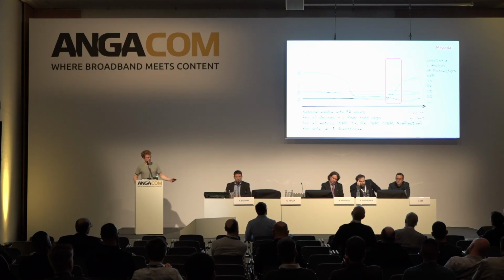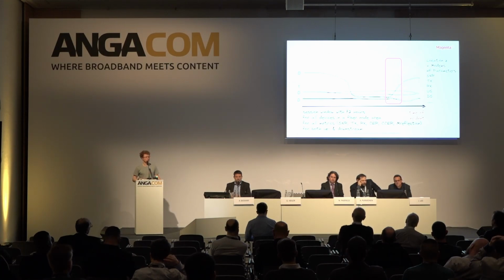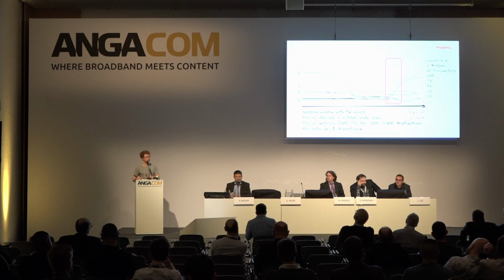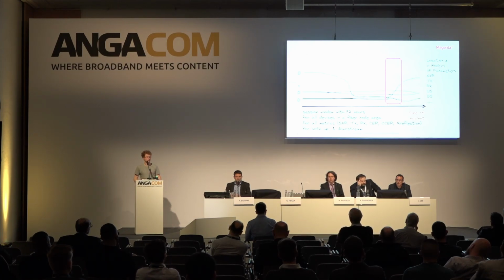On the x-axis, we see time as an abstract notion, where we have the state of the last 72 hours of telemetry data in the network leading up to the incident. We have many devices, all devices in that specific fiber node area, and multiple metrics for each device, being SNR, TX, and all of the PNM metrics you can imagine, in an aggregated way at the level of a last line amplifier. As this was the topological level, the feedback was available.